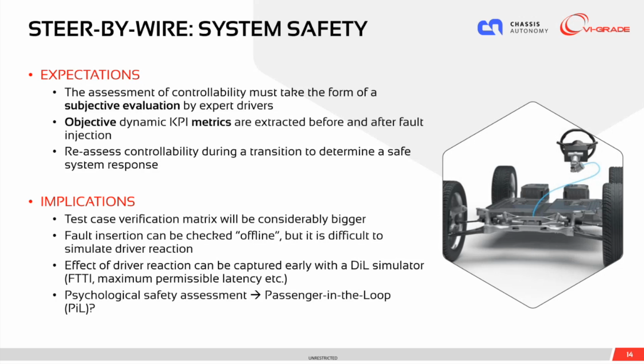You could argue, okay, I will do my fault insertion checks and extract metrics offline, but can you simulate driver reaction in your offline background scripts? Perhaps it's not so easy. And this is where driver-in-the-loop simulators come into play, where you can capture early driver reaction and also things like fault tolerant time intervals and maximum permissible latency evaluations.